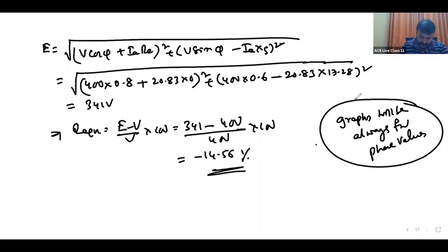One doubt is, sir, if it was star connected? Then the given voltage, in the data given, you always have to take as line voltage only. Always you need to take line voltage. In delta connection, line and phase voltage are both the same.